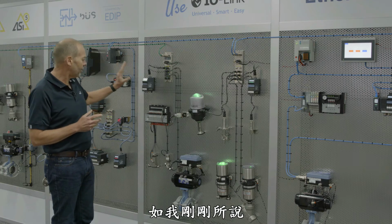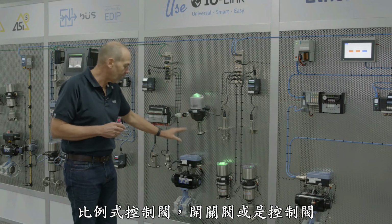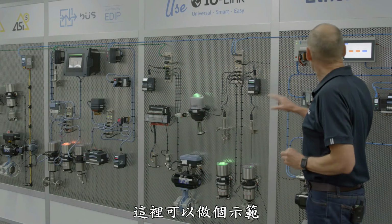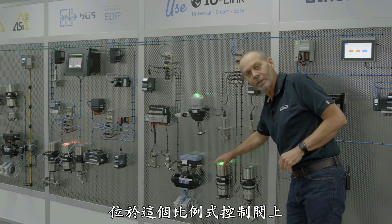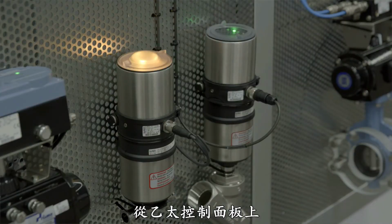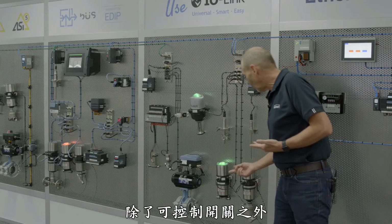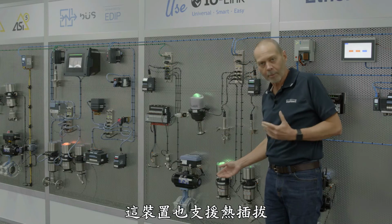So as I mentioned, you can control all of these different devices, whether they be modulating valves, on-off valves, or control valves. To give you an example, I will just operate this 8691 head, which is on a modulating valve here from the Ethernet panel, Ethernet IP panel, and I can operate and open and close that. So whilst I can open and close that, this is also hot swap capable.